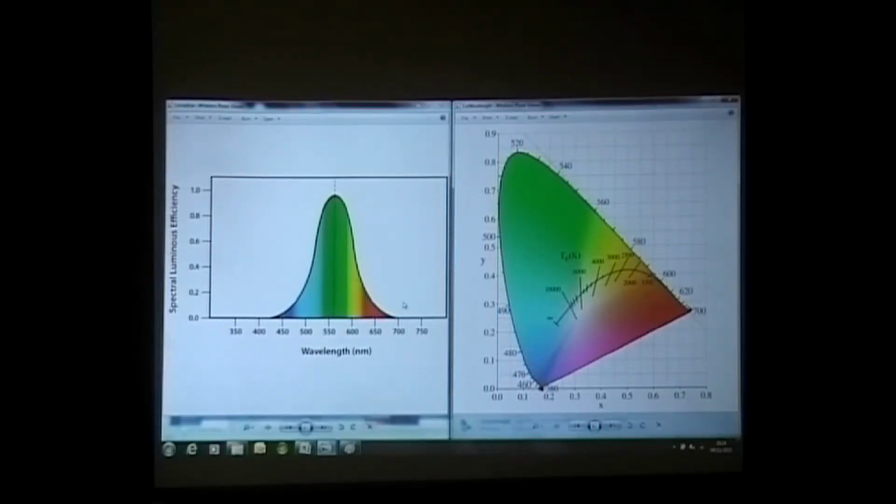And this one has just got some helpful stuff on, which we'll get rid of later. But this shows this line here is effectively the white line. So when somebody says, oh, it's a 4,000 K colour bulb, that's what it's going to look like there. When it's a 5,000, it's about there. When it's 6,000, you see you're going from what's called warm whites, which is your ambers, your yellows, down to cold white, which is your blues. So that's the white line. Obviously, perfect white is sort of where these three converge at around 5,760, which is usually what your monitors are calibrated on.